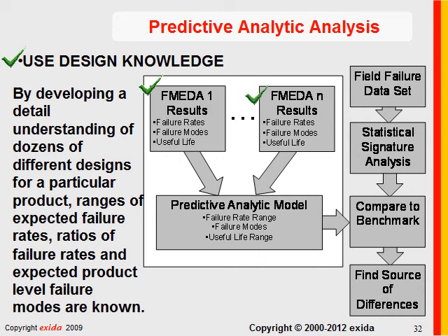When you look at the set of designs and put them into a tabular format, you start getting a very clear picture of total failure rate range for a pressure transmitter, failure modes and failure rates for each mode, and a useful life range. So we can say for a pressure transmitter, the failure rate should be between X and Y.